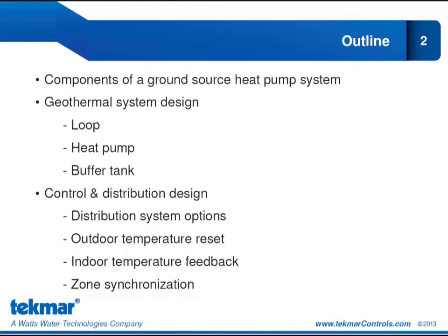So what type of terminal unit should we be looking at for a geothermal system? And then we'll start to look at some of the control features that Techmar has created to optimize the system, and that will include outdoor temperature reset, indoor temperature feedback, and zone synchronization. So each of those items will give you a better controlled system and will increase the operating efficiency of the geothermal system.